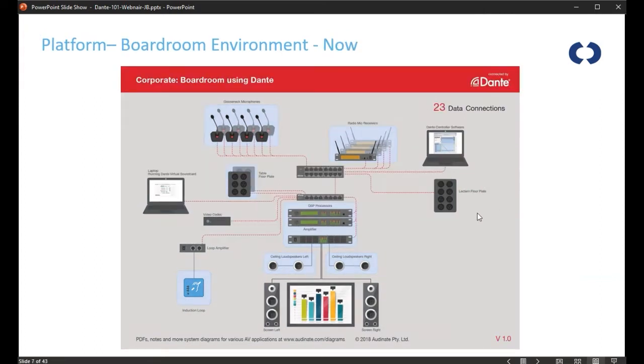Now, moving to what we currently see, quite a common trend now is you will run cat cable from a switch to a Dante device. And that cable obviously has its limitations, being 80 to 100 meters, 100 meters being really pushing it. But we now have distance advantages. We have means that we can transport audio over quite a long distance. We can distribute things. And also the D to A conversion or A to D conversion is happening at the hardware point.